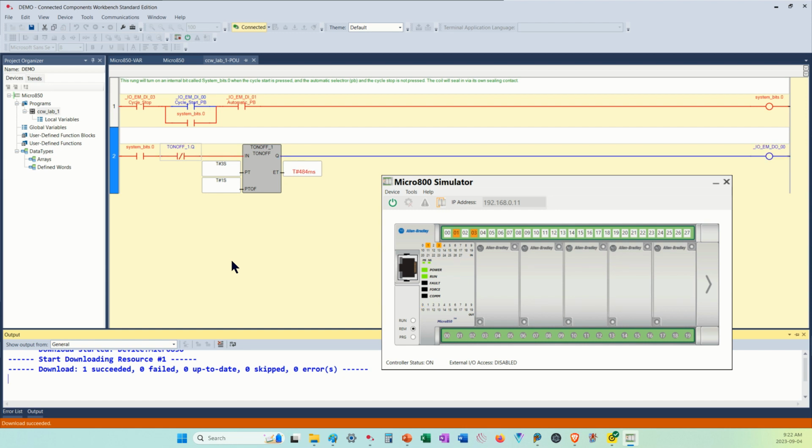So if you're using a common horn or a common light, this is a lot easier to work with, and it allows you to say, under this condition, I want a long horn with a short beat, and that pattern, everybody in the plant will know it's fire, or that this machine's starting, or it's a particular sound that's distinctive. Same thing with a pilot light or a siren alarm or any kind of annunciation.